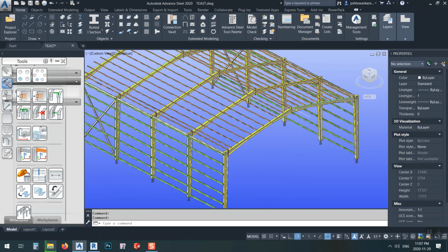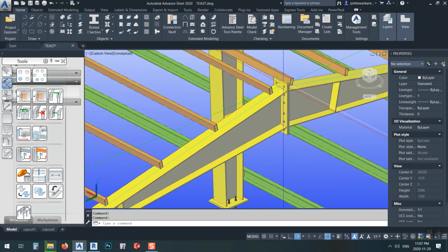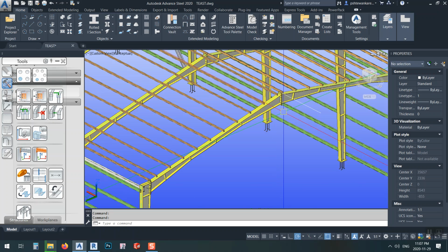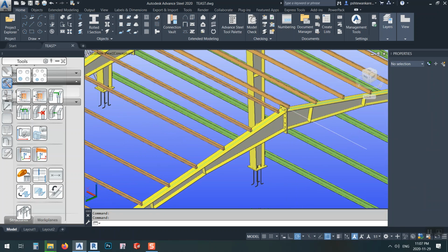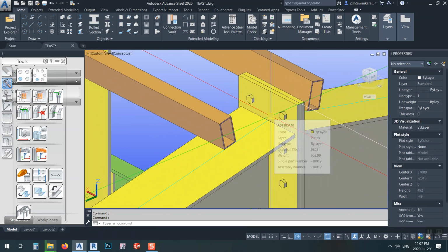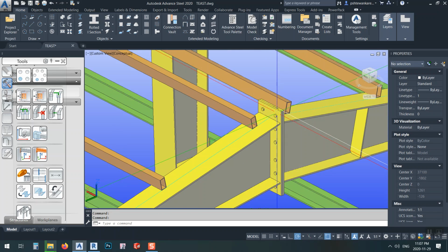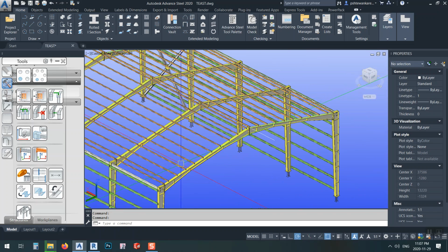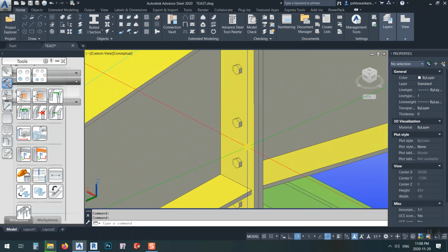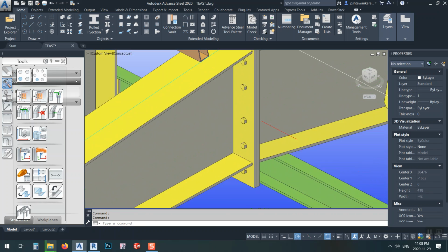You see, this way, if you don't know this one, do you know what will happen? You have to fix the first point. You have to specify the connection point. This is the point where these two beams connect, and after that maybe make a line, or maybe make new beams, and then arrange all these. And as you saw, I didn't delete anything, however I could delete one connection and remake it,